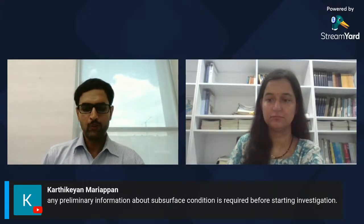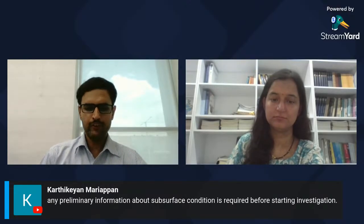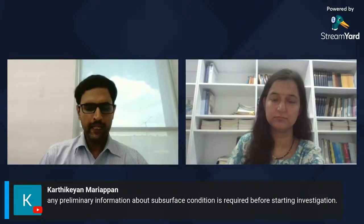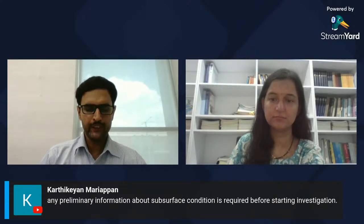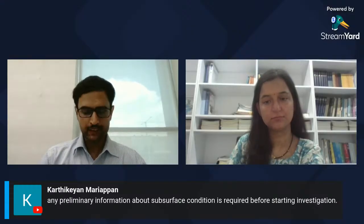But sometimes, if we don't have any information about the site, usually we would have to first plan a certain amount of boreholes or a certain amount of CPT soundings to then get preliminary information from which we can then refine or customize future investigations for that site.